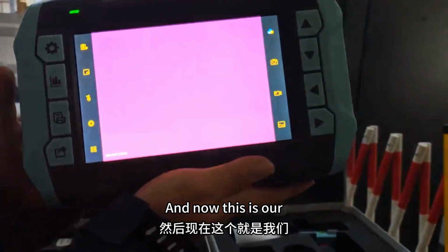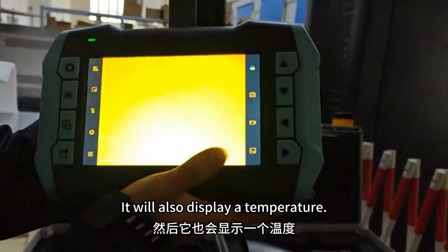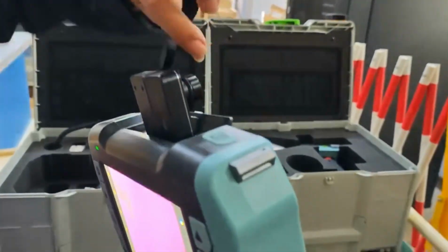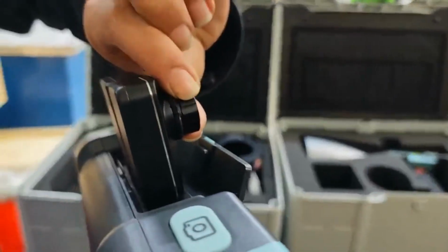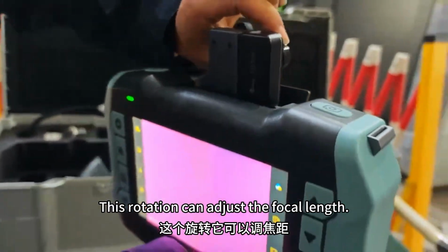And now this is the infrared test interface. You can also take photos here. It will also display a temperature. If we want to adjust the focal length, rotate the knob on the front of the lens, the front part of the lens. This rotation can adjust the focal length.